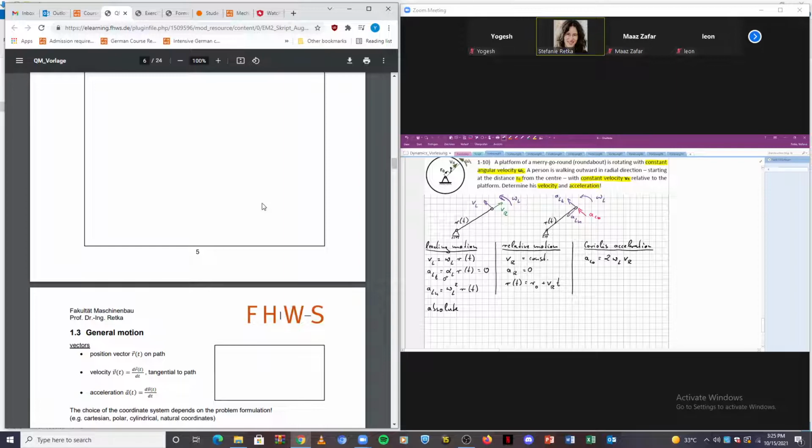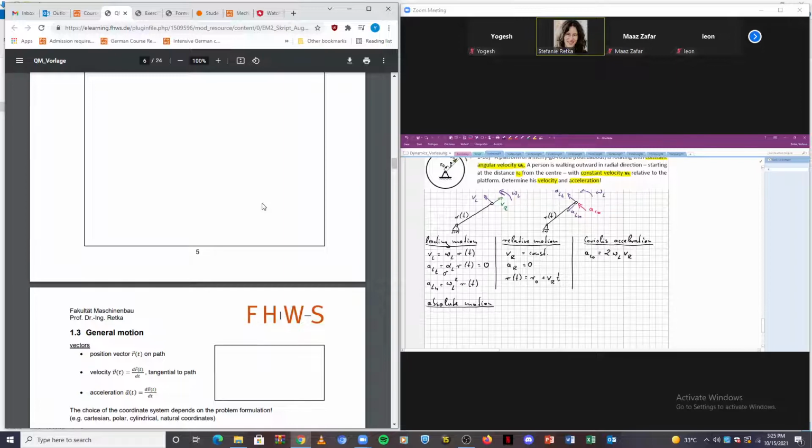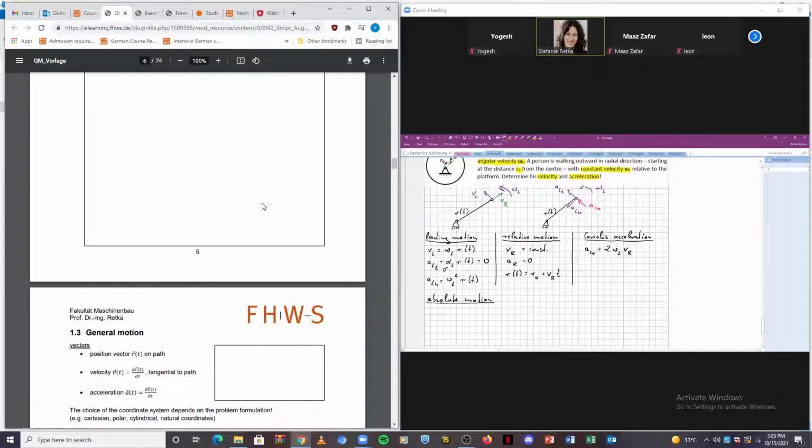The absolute motion. We'll start with the velocities. And again, we will first state the general equation as a vector equation. So it's VL plus VR, vector addition of leading and relative motion. In our case, leading and relative velocity vectors are perpendicular to each other.